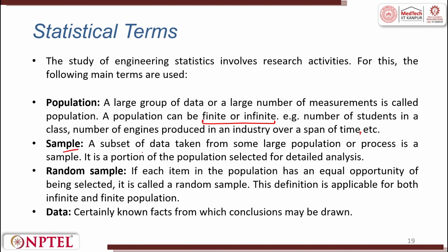A subset of data taken from some large population or process is a sample. It is a portion of the population selected for detailed analysis. As I said, for example, in the manufacturing of a nozzle, there were 100 nozzles. We tested only 5 out of them. That is 5% of the overall population. The 100 total size, the population, is also called the lot size, and we have 5 as the sample size.